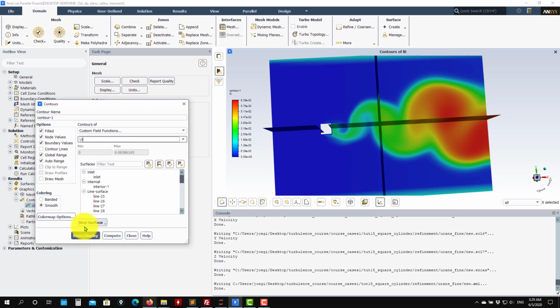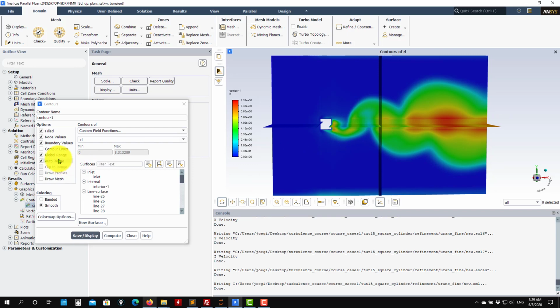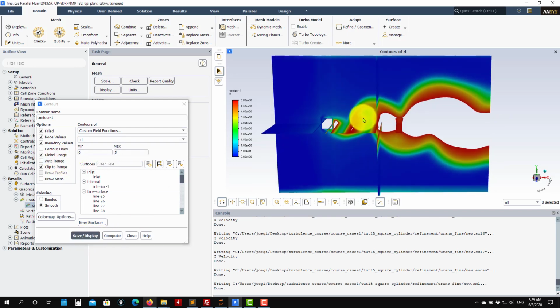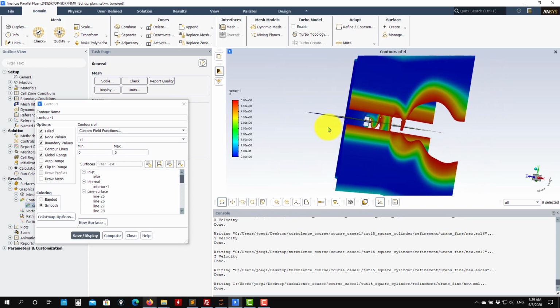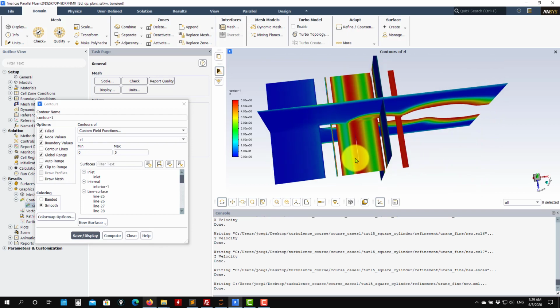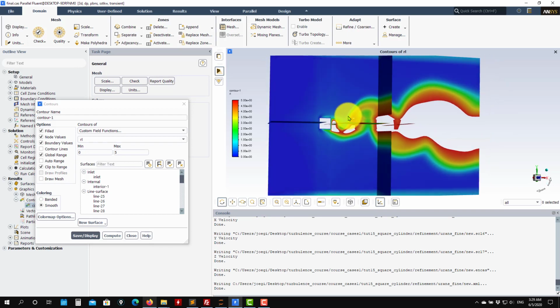And then if we put RL, this is the one that gives a refinement ratio. With auto range, see that everything above 5 is what is resolved. So here in the far wake, it's telling you that it is resolving well, but here something is missing, so maybe we can add some refinement here.